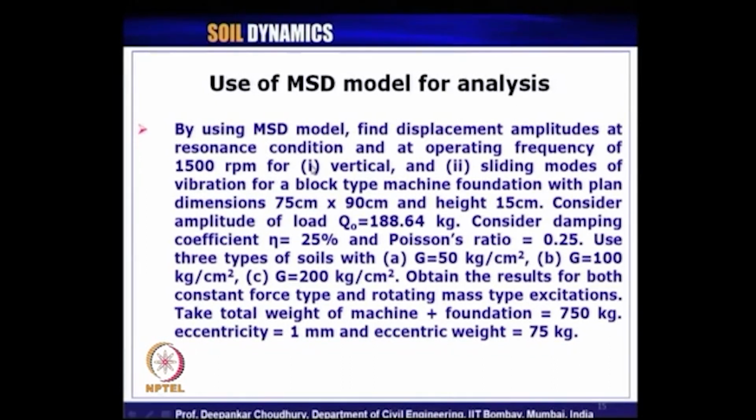For vertical and sliding modes of vibration, for a block type machine foundation with a plan dimension of 75 centimeter by 90 centimeter and a height of 15 centimeter, that is whatever we had designed using Chebotarev's reduced natural frequency method, now we are checking that foundation.